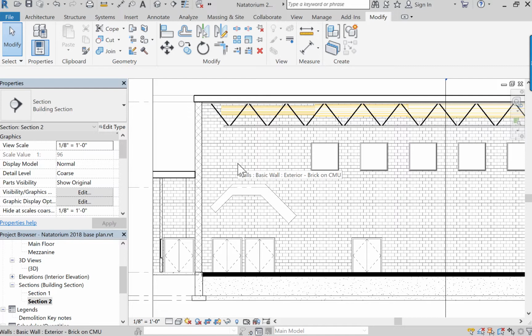If you want to use something like stadium seating, that is typically a hosted element. So be sure to create the mezzanine floor construction, which will be tiered, so it will be sloped. Be sure to create that using some sort of either extrusion or mass to make your shape, and that way the floor furniture will go directly into it.